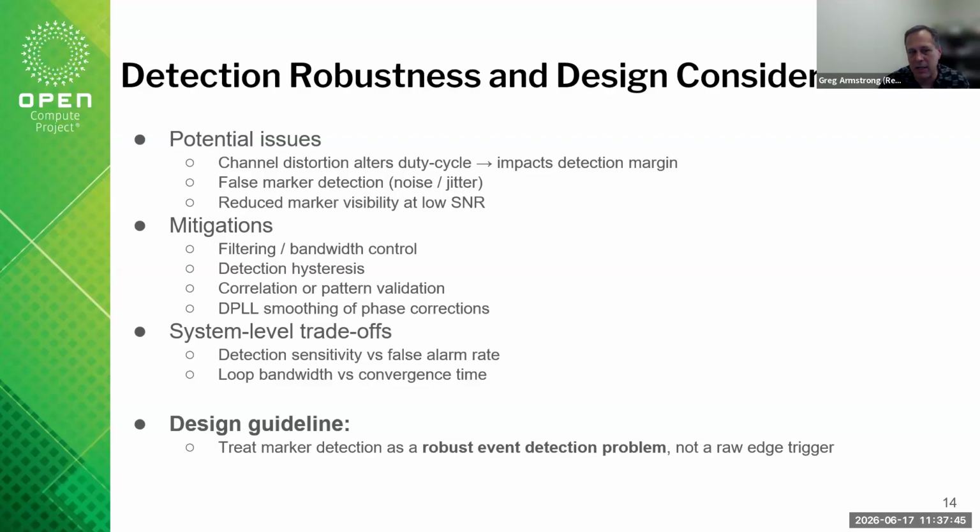It may just temporarily speed up or slow down to mitigate that change that may be detected because maybe there was a failover. You went over to another time source. It slightly is off a bit different from where it was from the other time source. So you want to try to transition and track it using more PLL capabilities than trying to manage it through counters or subtraction or addition, and make sure you don't do something like go backwards in time and things like that, or even repeat time, right?